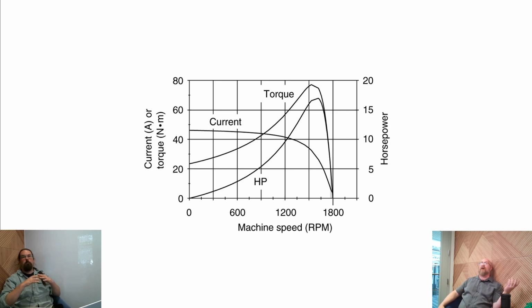So you're getting, through context here, hopefully, the beginning ideas of what we're talking about when we talk about slip. One of the things you'll see is that we get this peak right before our maximum rated RPM, and that's the synchronous RPM. That means that's where it stalls out. If you hit synchronous RPM, there's no longer any torque available at all. Which is why an induction motor technically always has some amount of slip, unless you lock the rotor.